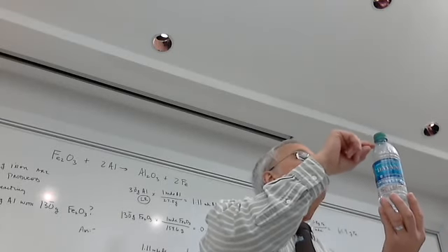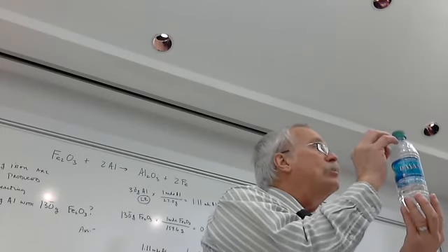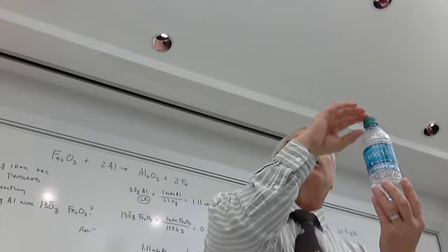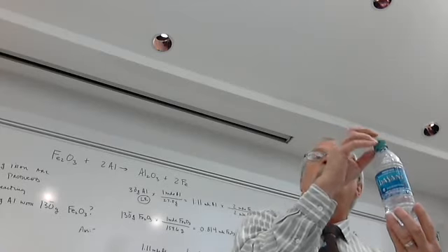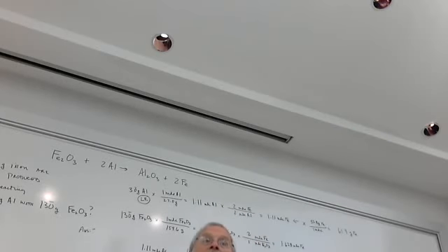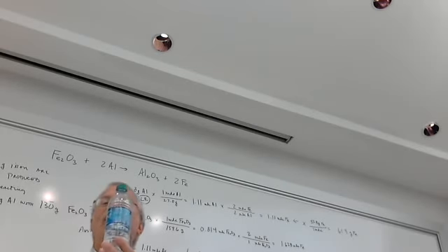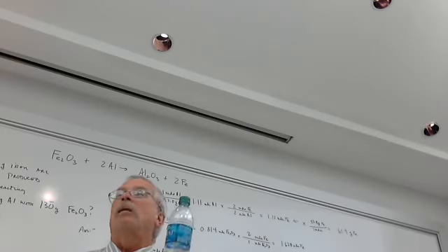If there's a little airspace there, that liquid expands into that airspace, and the gas up there is compressible. It can be squunched, it can be compressed. The liquids cannot. So if we had filled our bottles completely, giving the consumer every cent worth of bottle that they have liquid in there, we'd be having broken bottles everywhere.